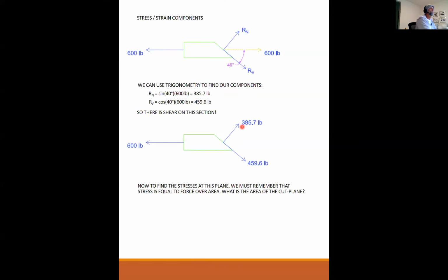And also remember, maybe I should say this. The normal force, positive or negative on the normal force, has an important meaning: this is in tension. If the arrow was the other direction, it would be in compression. Positive is telling me tension. The other direction is telling me compression. And that has a very real physical attribute to positive or negative.